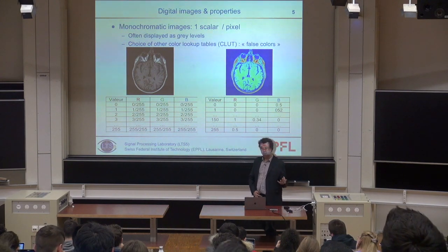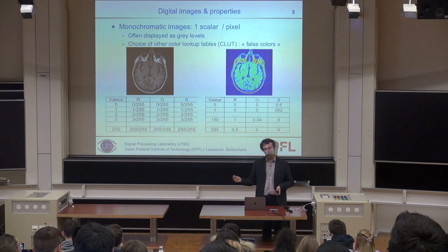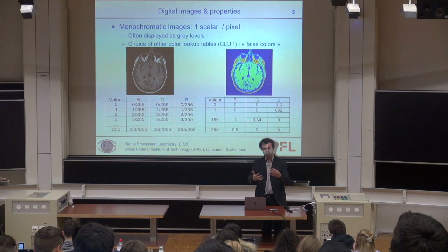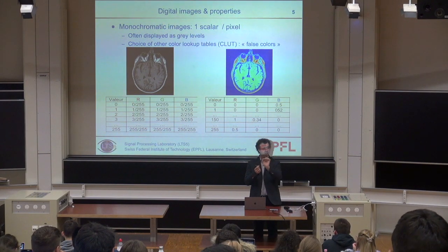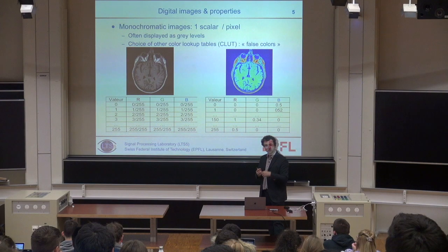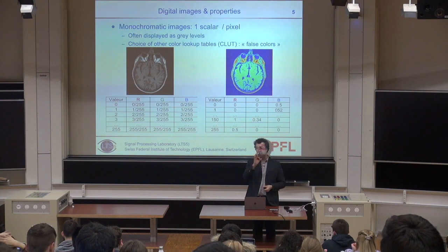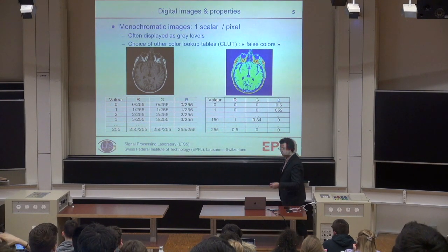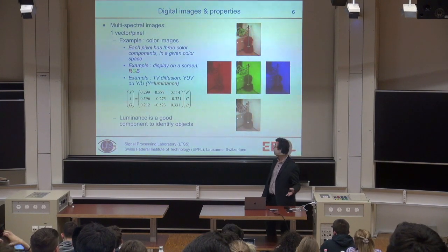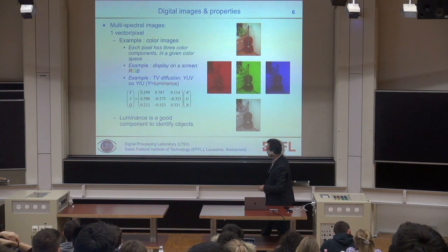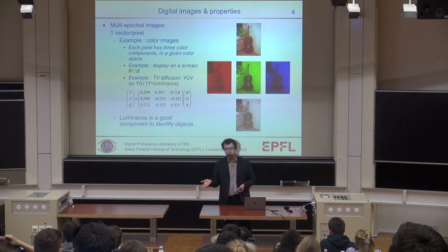But now if you have a camera that acquires a color image, typically an RGB image, so the amount of red, green, and blue that the sensor will receive. This is very simply done by having 3 sensors for each pixel, each of them with a filter that will only count the amount of energy that they have in the 3 color channels. So for each pixel, you have a 3 CCD, for instance. So 3 sensors with a filter that will just count how much information you have in the 3 color channels. Then what you get is per pixel 3 values. So we have color images where we have RGB here. And so what you natively receive when you capture that image is each pixel with 3 values, RGB.